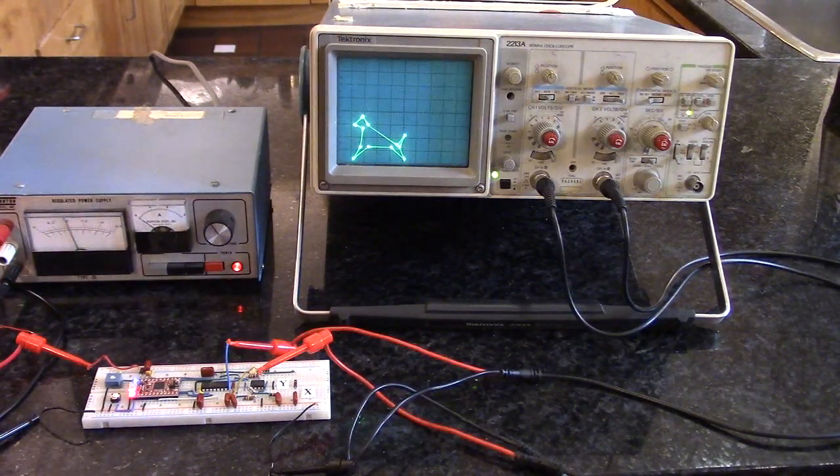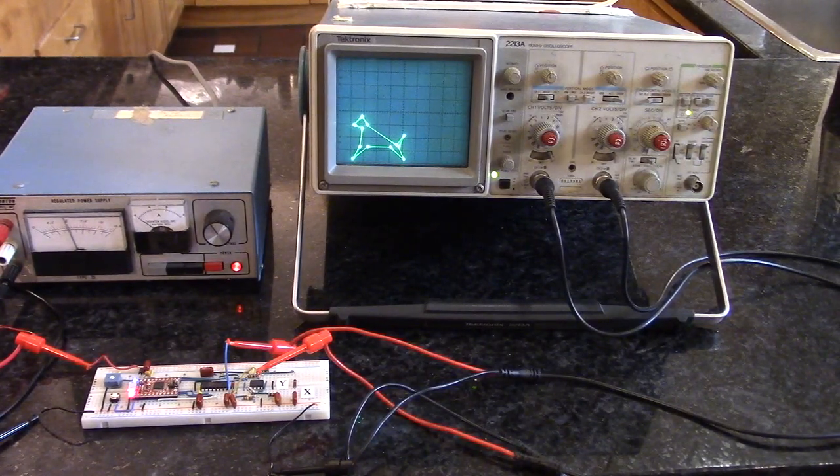But the book talks about using a multiplying DAC so that we can get a zoom effect. Now, a multiplying DAC sounds fancy, but all it really is, is a DAC where instead of using a fixed reference, you put the reference in, and the reference can go from 0 to some maximum value. And what that means is that the output of your DAC goes from 0 to whatever the reference is. So if the reference is 0, you just get 0 out all the time.